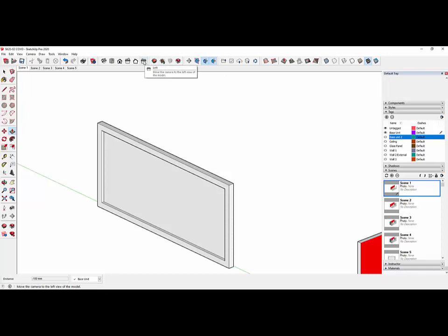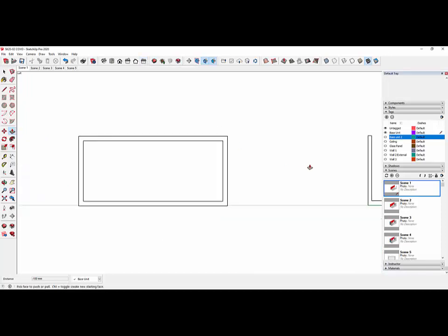So if we go back to the elevation view, we can actually see the wall itself. If we click on the tape measure, we can use the tape measure to create guidelines. So it's very good for how we set out. If you're going to cut an opening into a wall, you want to set it out. So we can create those various points. By clicking on, you can see that we can actually add the guideline itself.